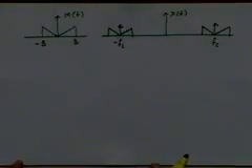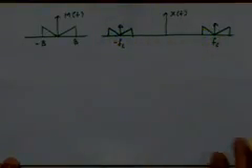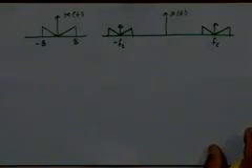So the only way the spectrum of the AM signal differs from the spectrum of the AM signal with suppressed carrier is that this carrier component is not present there. I hope that also answers a question as to why we call the earlier kind of signal DSB-SC, right? It is basically this difference.